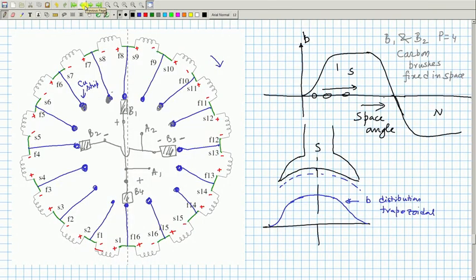And in DC machines, the armature winding is slightly difficult, unlike AC machine windings. But although the basic features of a winding are still present, that is, each coil will generally be a full pitched coil, and they will have two coil sides, and the separation between these two coil sides will be 180 degrees electrical.